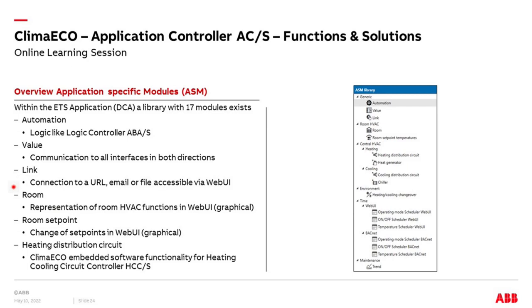So then we have this room ASM, remember, just shown already, representation of the room in a graphical way with all HVAC functions behind related to the application controller, easy to operate, easy to see the actual status, quite user-friendly. Room set point is change of set points in the WebUI for room temperature.